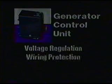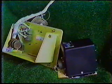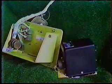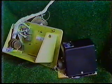The brains of the generator circuit is the generator control unit. This small black box incorporates the functions of voltage regulation, circuit and airframe wiring protection, and other critical functions. The generator control unit also contains fault protection circuitry, nearly identical to that used in the battery fault system. There are two generator control units, one for each generator installed in the aircraft. These units must talk to each other in order to keep the output of each generator equal, or in parallel. The paralleling function is the only connection between the two totally independent generator systems.